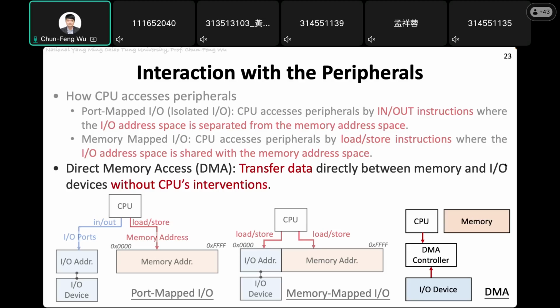Oh, so there is a version of this table on the NAND chips. The translator in the FTL cannot directly access the mapping table on NAND. It is possible, but it is slow. If the table is in the DRAM, why not just directly access the DRAM? DRAM is quite a lot faster, I would say about three orders of magnitude. Oh, okay, that's all. Thanks.